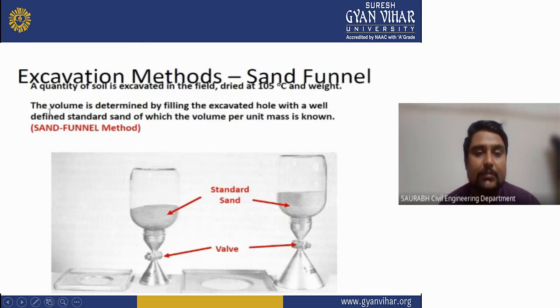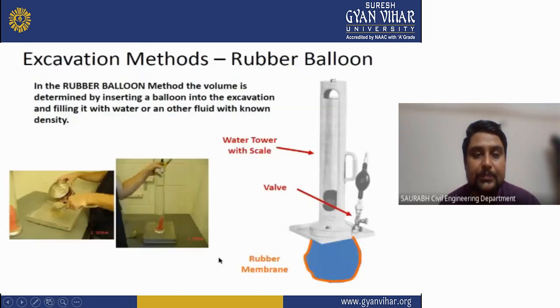The volume is determined by filling the excavated hole with a well-defined standard sand, of which the volume per unit mass is known. This is the sand funnel method. As you can see, this is your sand funnel method, which is used for excavation purposes.